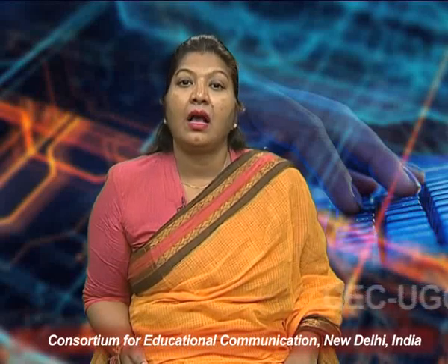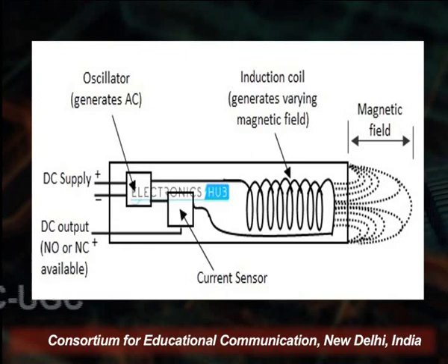There are four components of the inductive proximity sensor: an inductor or coil, an oscillator, a detection circuit, and the output circuit. The inductive proximity sensor generates a fluctuating magnetic field using the oscillator and the winding coil, which is located on the sensor face. Here, see, this is the inductive sensor. When an object moves into the field of the inductive proximity detection area, eddy current will build up and the material will reduce the inductive sensor's magnetic field.